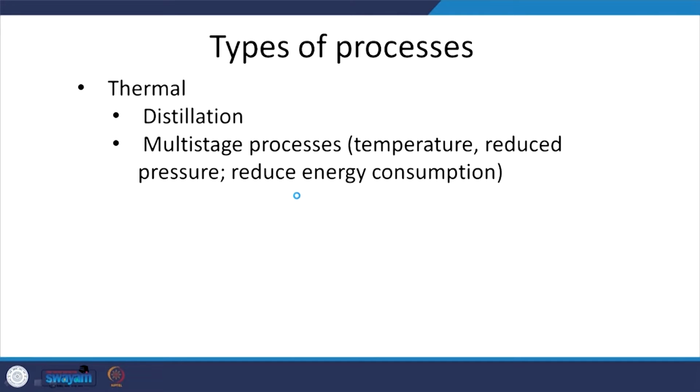So, different types. One is thermal distillation, something that people would have come across. Distillation is typically energy intensive, you need a source of heat so that you can convert the water into water vapor, and then as you pass it through, the relevant salts are not going to be converted into the gaseous phase, they are going to stay as solid.